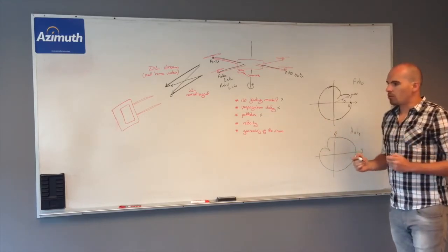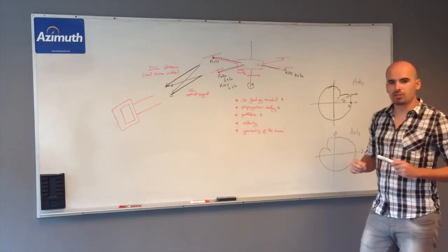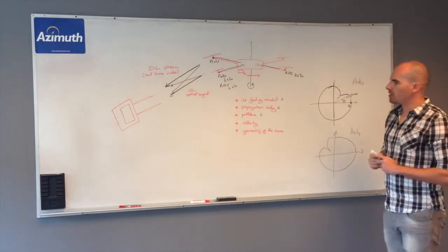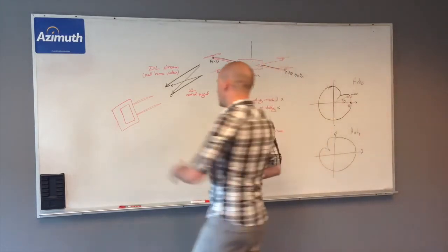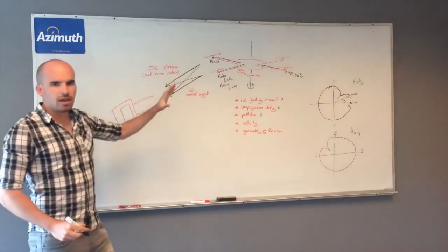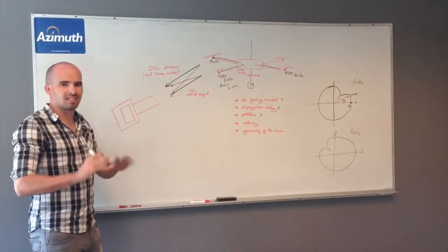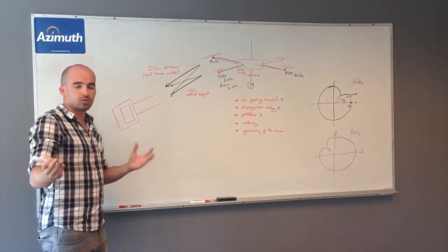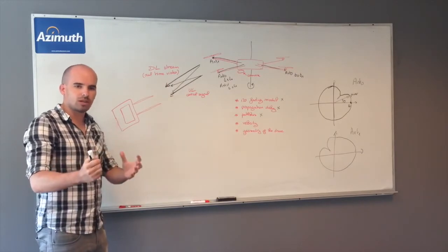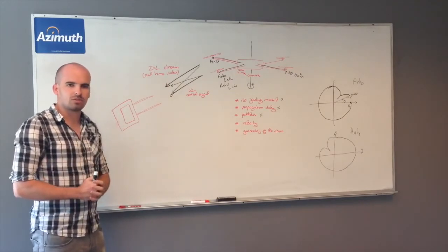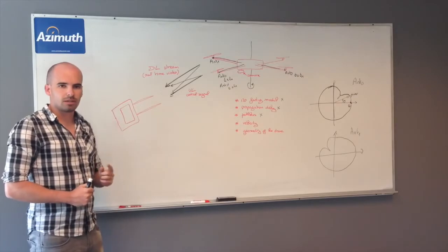The other way to do that would be to go into an anechoic chamber. By going to an anechoic chamber, you could take your controller and your drone, and do this test for every degree. When you get all those very clear data, you can use the same approach as Field-to-Lab: take those values, put them in a CSV file, and replay those values again and again.